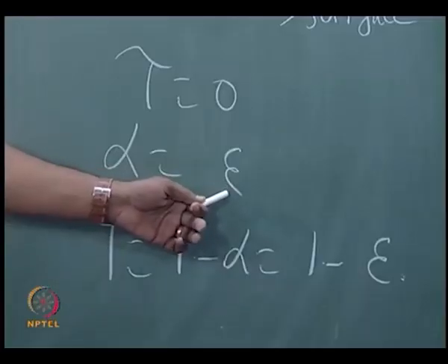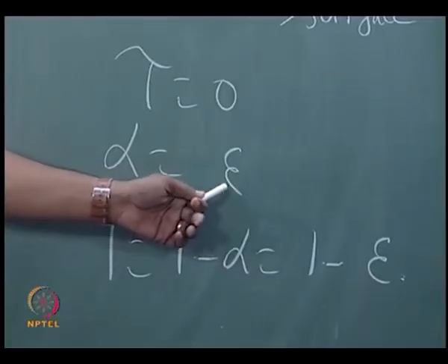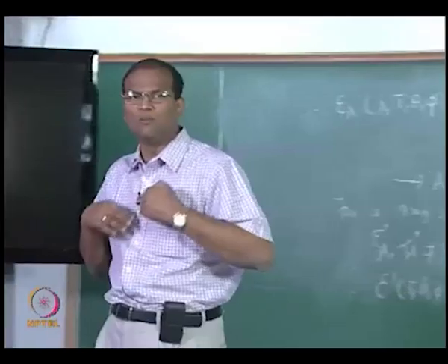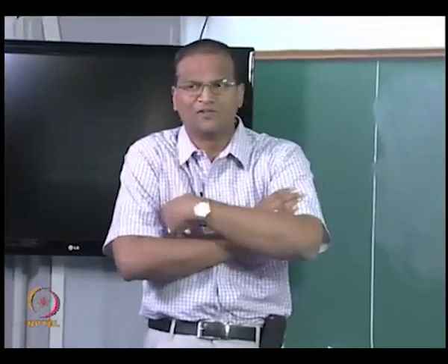So from handbooks or data books or from experiments, or somebody tells you what the emissivity of the surfaces are, you can calculate the absorptivity, you can calculate the reflectivity, you can proceed with the detailed radiative heat transfer calculations.